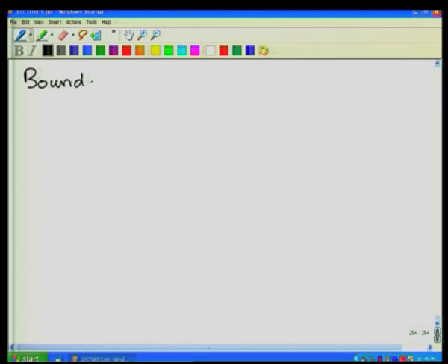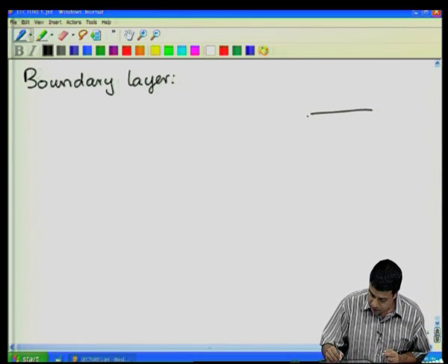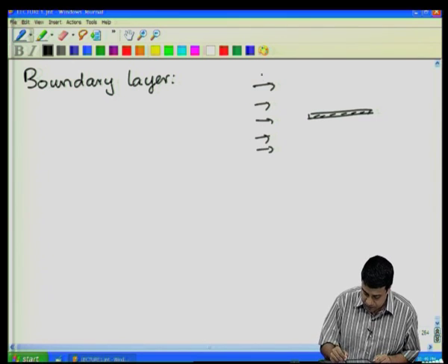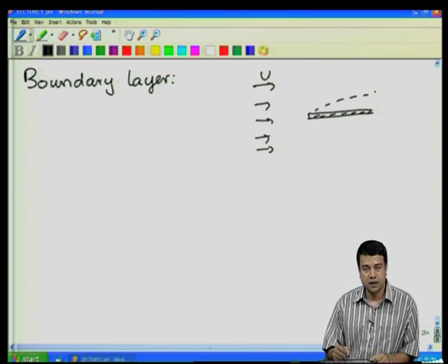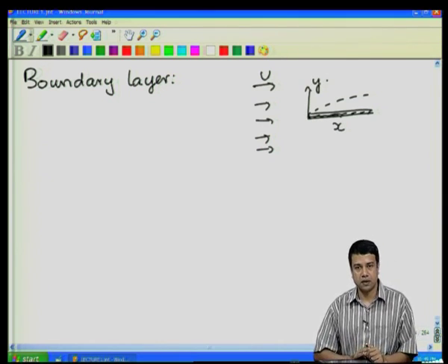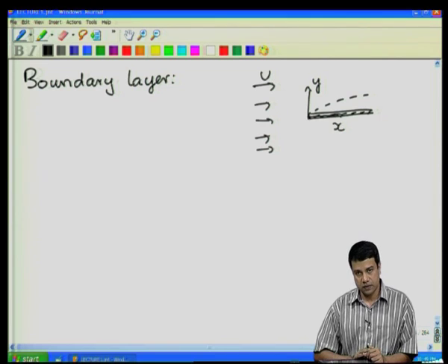The simplest boundary layer that we looked at was the boundary layer for the flow past a flat plate. Now, you had a constant velocity U coming in, and there was a boundary layer here. This is the streamwise direction, the cross stream direction. If you just use the outer potential flow, that would predict that the velocity is equal to capital U everywhere. However, that does not satisfy the no slip condition at the surface of the plate itself.